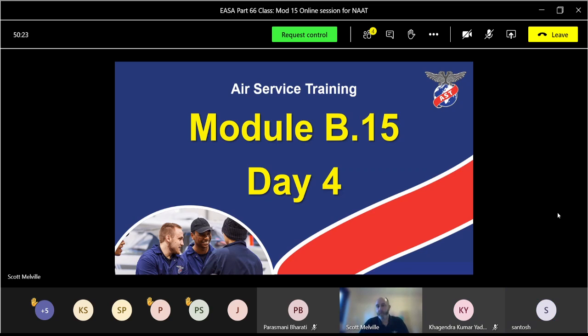So as we go up in altitude, it's got sea level pressure inside it initially. When we start going up in altitude, what's going to happen to the capsule? Will it expand or contract? Expand with the altitude. Yeah, it's going to expand, and as it expands, it's going to push this bleed valve off the servo line, which is going to bleed the servo pressure and reduce servo pressure, therefore pump output will also reduce.